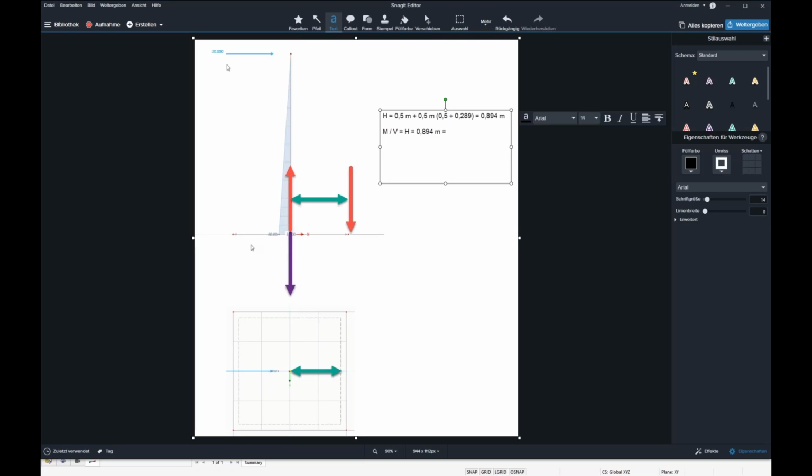And this we write in more detail, what means this M is maybe a horizontal force, so F multiplied with 3 meter length, divided by the vertical component of 26.75 kilonewtons. And if I calculate now the F, I receive 7.97 kilonewtons.